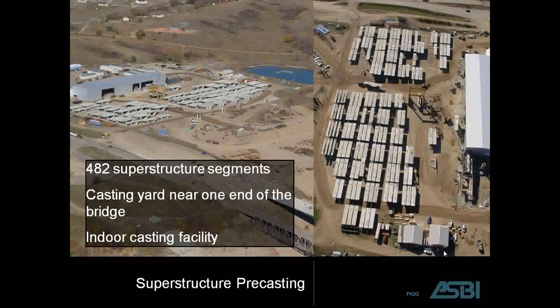This next slide shows the precast operation from a distance. In the picture on the left, you can see the storage location. I'll get my cursor up here. You'll see the segments in storage, but also you'll see the shed behind the storage area, and that's where the segments are actually being fabricated. The picture on the right shows more of an aerial photo, and you see the segments that are in place. The wider segments here are the typical span segments, and the narrow segments are the pier segments because they, of course, weigh more and require a lighter section for lifting.